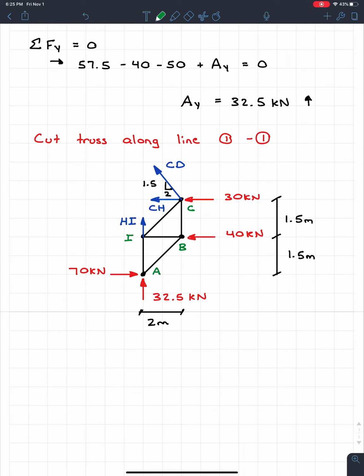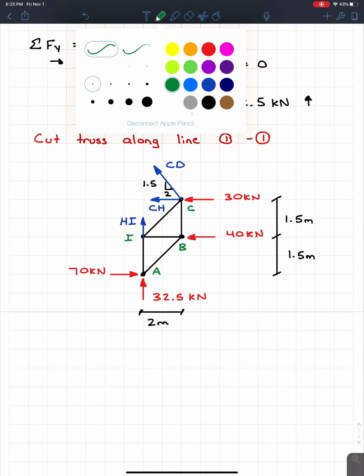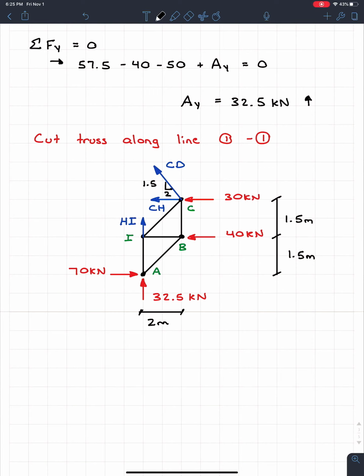So if I'm looking at this, I have a free body diagram, it's good to go. I have 3 equations, and if I look here, I have 3 unknowns. So this works out actually very, very well. So now I can start going through and solving these forces. And the nice thing about trusses is there's actually a lot of ways to solve for these very, very quickly. But I'm just going to go with whatever I think is obvious, and then I'll show you some tricks at the end to solve for some of these forces. Because there's kind of one big one with trusses, as you guys will see, and you guys are going to hate it. It's not a nice thing because it requires thinking outside the box. And that's something students don't like to hear. They prefer a more straightforward approach. So they don't like hearing that they're going to have to think really hard.